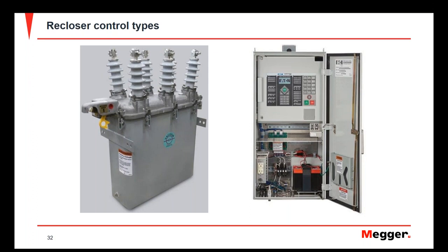Now, during an overcurrent condition, the coil is going to control a plunger that's going to open the recloser contacts, and the timing and the sequencing events are going to occur by oil being pumped through separate hydraulic chambers within that recloser.